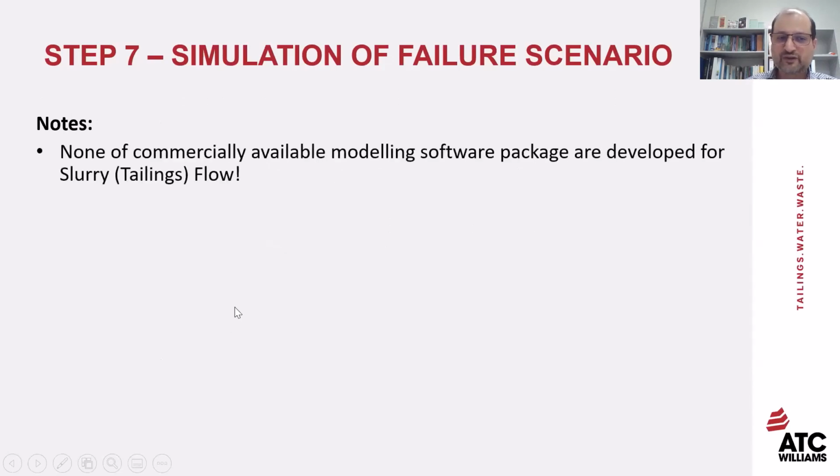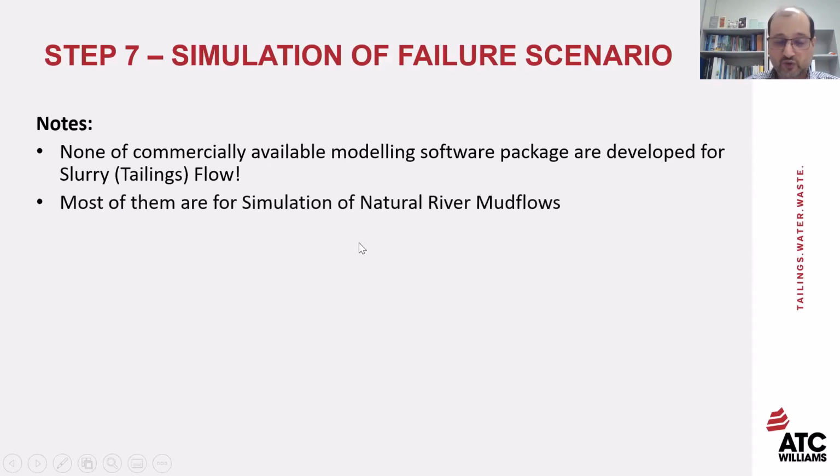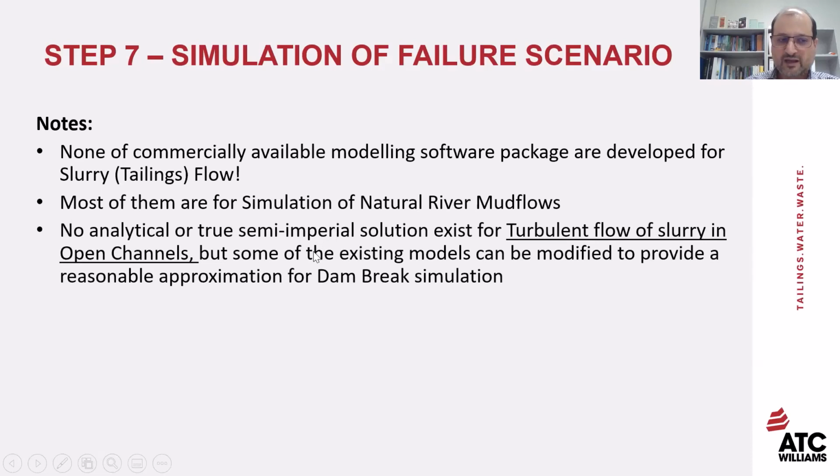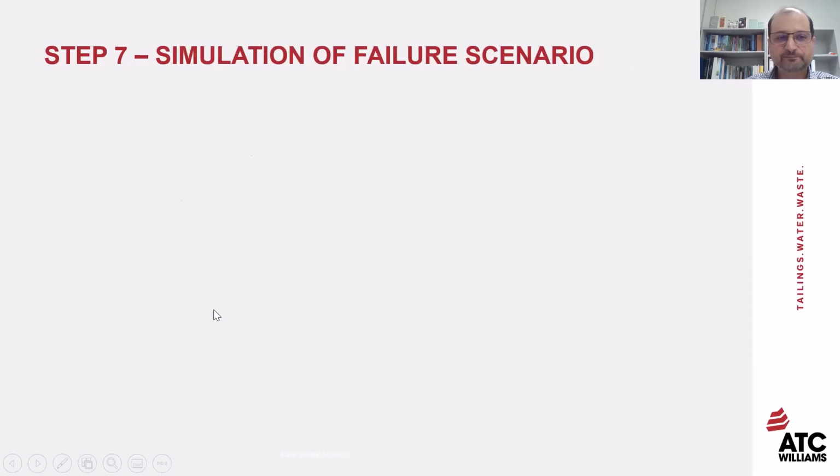By using those software models, we have to know that none of the commercially available model software packages are developed for the slurry or tailing flow. Most of them have been developed for simulation of natural river mud flow. And there are differences between the two simulations. No analytical or true semi-empirical solution exists for turbulent flow of a slurry in open channel, but some of the existing models can be modified to provide a reasonable approximation for dam break analysis.